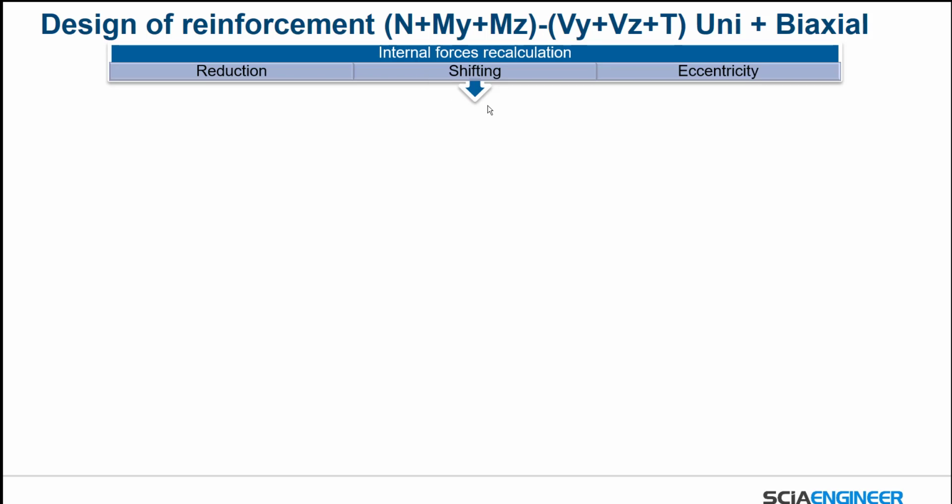Also we can increase some reinforcement. The longitudinal reinforcement can be increased due to the shear, and this is what we call the shifting rule. This is from the Eurocode. And also when we design any compression member like a column, then SCIA will take something we call eccentricity to magnify the amount of bending moment on that member to meet the requirement from the Eurocode.